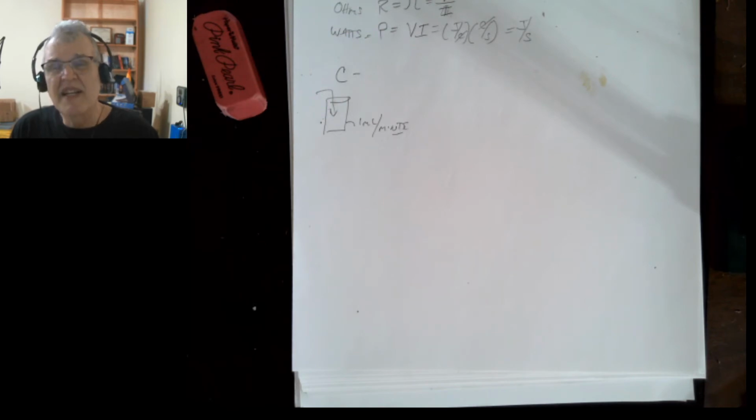It's usually a C rating. C rating is charge or discharge rate relative to the capacity of the battery. Capacity. So what is capacity? Again, capacity is given in amp hours. Most manufacturers will calculate the capacity at 0.2 C.